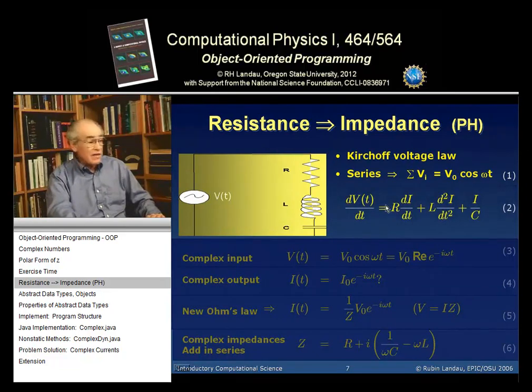If we apply that law to this circuit, we get equation 2. To be fair, applying the law gives the voltage drop across the capacitor involving the charge on the capacitor, and that gives us an integral differential equation to solve, which looks terrible. So in equation 2 we've simply taken the derivative with respect to time of Kirchhoff's law, so we get everything in terms of current.